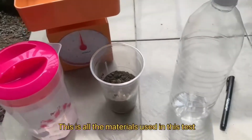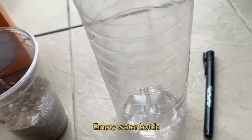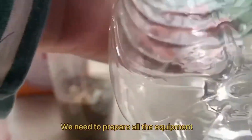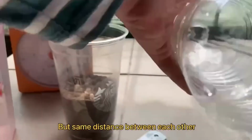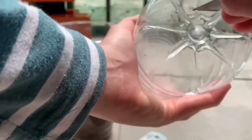This is all the material used in this test: a jug of water, soil sample, empty water bottle, and a weighing scale. Before conducting the test, we need to prepare all the equipment. Label H1 until H4 with different heights but the same distance between each other. Then make a hole at the bottom of the water bottle using a knife.